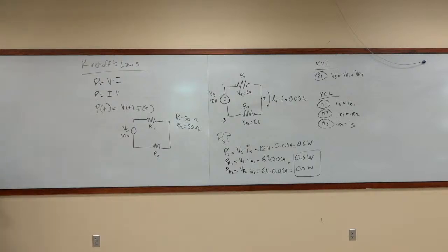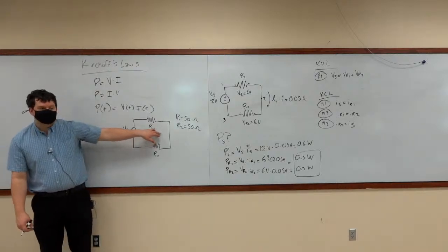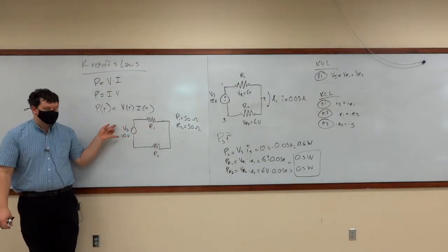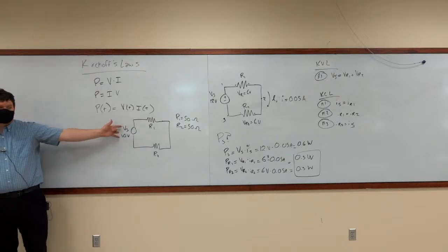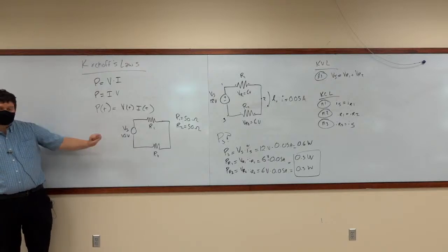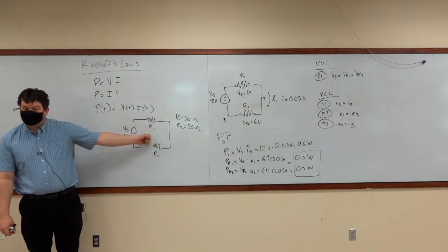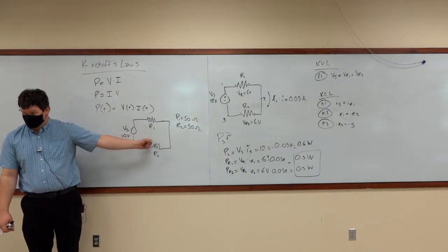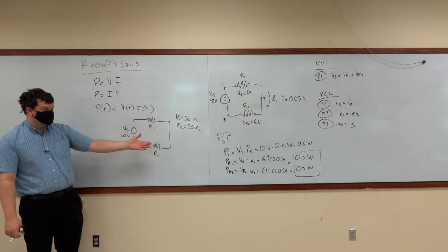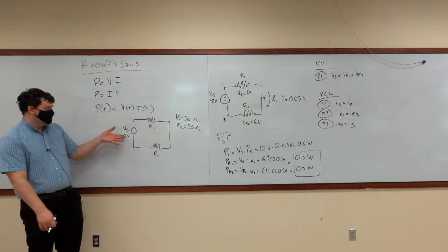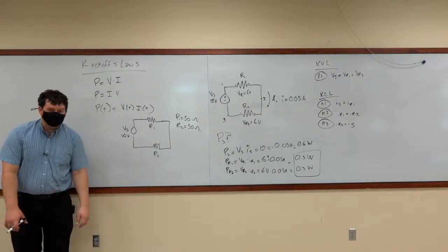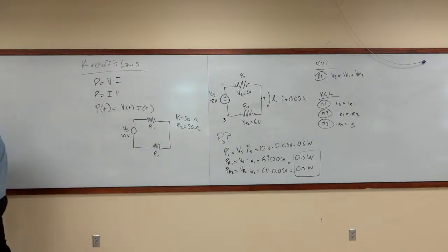You need to know not only how much power is being consumed by this resistor, but also how much power is being supplied. What are those power values? In order to figure out the power values, you have to figure out the current. Here, you don't know what the current is or the voltage is across this component. You only know the resistance. And you know that it's plugged into a circuit that has 10 volts put across it. Okay?